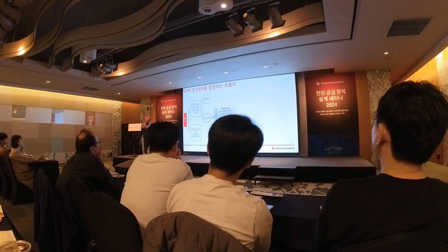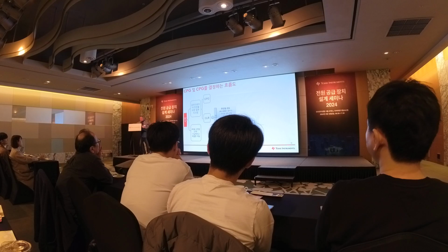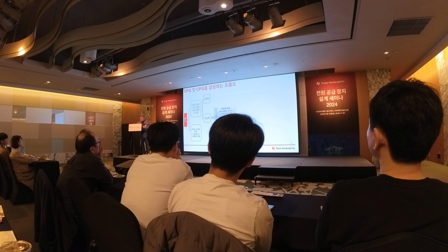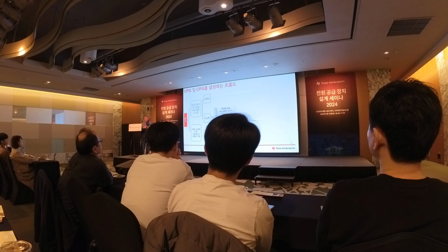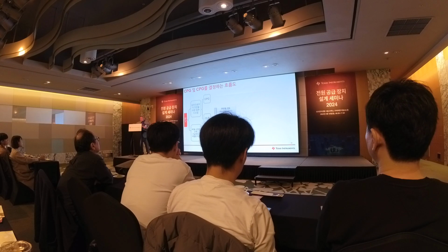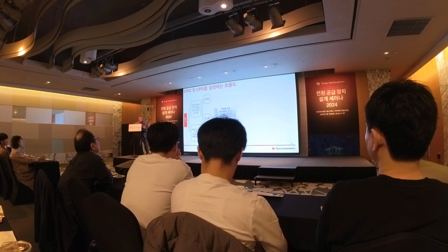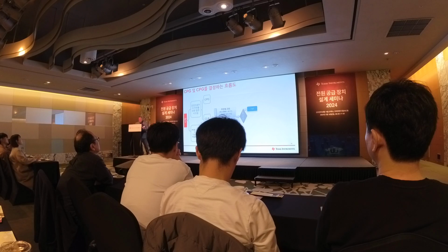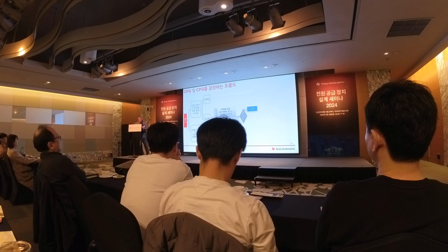So we're going to start first with the clearance. The first thing we do with the clearance is we need to determine the mains transient voltage, we need to determine the pollution degree, and we need to determine the altitude above sea level. So once I know what those are, the next thing I can do is I can decide whether it needs basic or reinforced insulation.